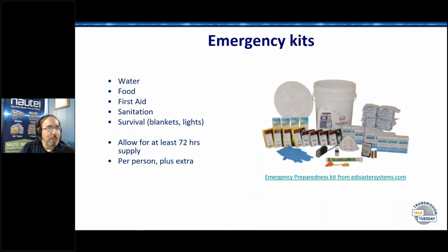Now, Alex, before you leave, on that particular transmitter, they use those bladder style pressure vanes. The air blows through it and pushes the switch. I've seen guys just wire right past those things, which in those types of transmitters is extremely dangerous. Yeah, I've walked into them where there's either been cardboard between the reed switches or paper clips across them, depending on whether they were normally open or normally closed.